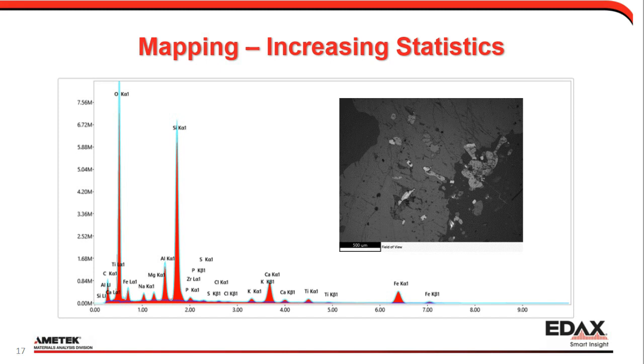basically. It's a ceramic, so we have our primary elements being oxygen and silicon. But then we have a bunch of other things in there. There are some iron inclusions and calcium inclusions, aluminum. There's some salt in there, sodium and chlorine, probably mostly from dirty fingers, as we've been using this sample for a while. And we also have a phosphorus and zirconium overlap, which makes this one pretty interesting. That is the small peak you see just on the right-hand side of the silicon peak.